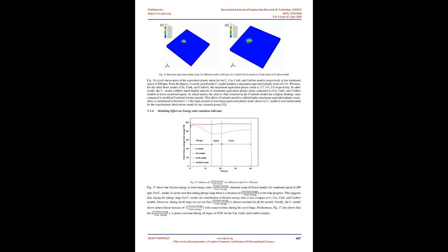3 rotational speeds were considered: low rotational speed, 200 rpm, moderate rotational speed, 350 rpm, and high rotational speed, 450 rpm. All 3 weld schedules have the same weld speed of 1.27 mm/s and same rate of plunge, 0.4 mm/s. These rotational speeds were chosen from published experimental results 32. Following are the experimental observations of the welding schedules that were analyzed in Table 6.